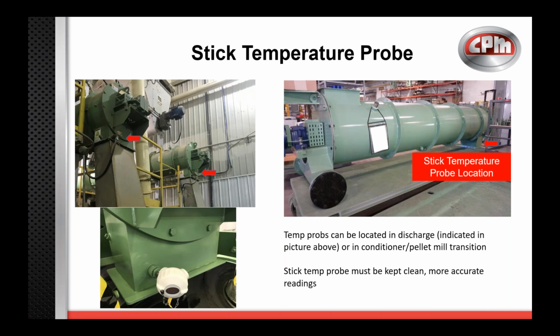whereas with the stick probe, if we're using our standard 60 seconds of retention time, you might adjust your steam, but then you won't see a response to that for at least 60 seconds. Something else that might delay that response is that, since it's a stick that sticks out into the discharge, materials could potentially build up on top of it and again act as an insulator and not allow timely, accurate readings. So it's important to keep both of those clean. The stick probe might have to be manually cleaned just because of its location, and that's simply wiping it off, but don't pull too hard on it, as you could potentially bend it.